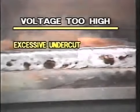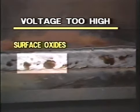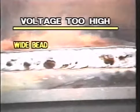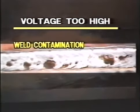High volts will result in unacceptable undercut. Excessive surface oxides are also usually an indication of too high a voltage. Weld bead width increases as voltage increases, resulting in lower penetration. A longer arc length increases the chances of the weld droplet, as it is traveling across the arc gap, picking up contaminants from the atmosphere.